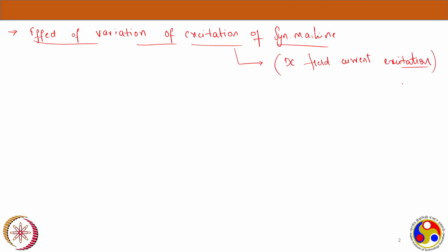Now we will be discussing all the concepts in it. But before we start, let's make a quick assumption to make the analysis a bit easier. In the equivalent circuit of a synchronous machine, as we saw last week, there is a series resistance and a reactance on either side of the excitation voltage as well as the bus voltage V. But for simplification, we are neglecting the armature resistance Ra and assuming it to be zero, because it just makes the concept easier to understand.